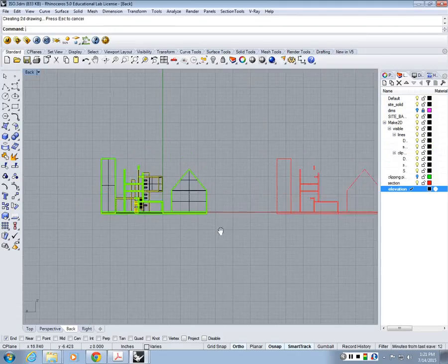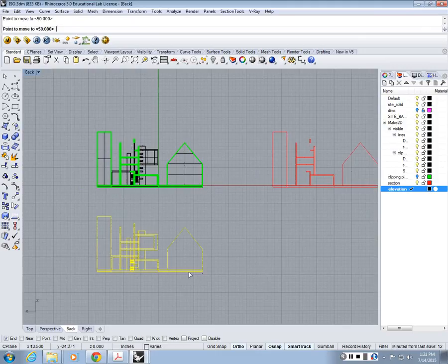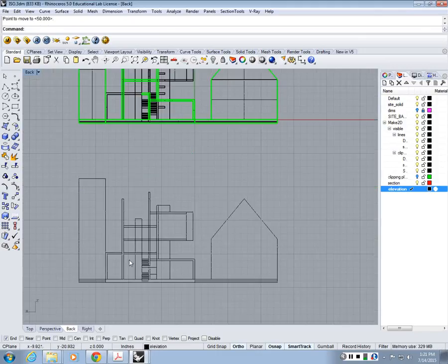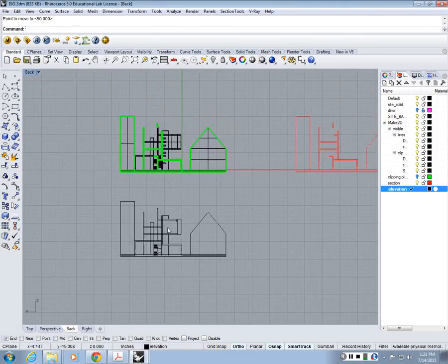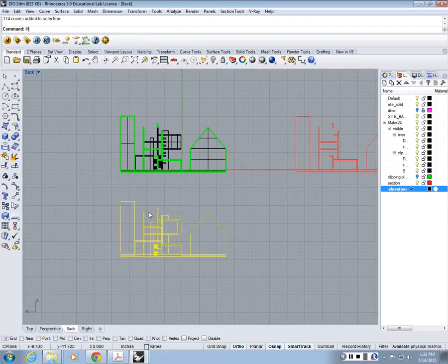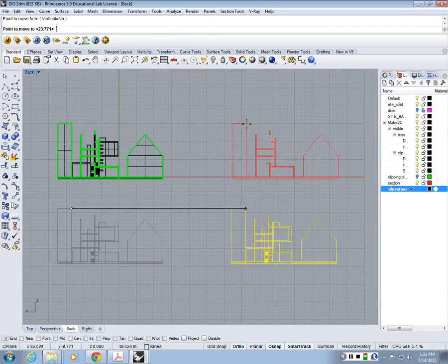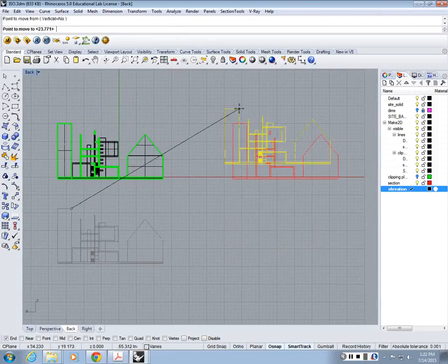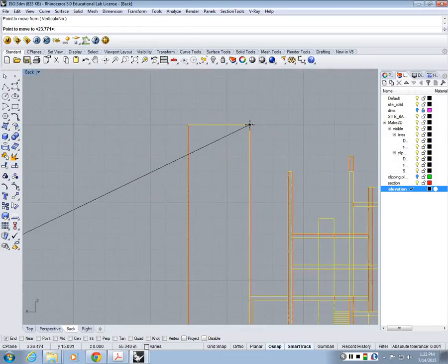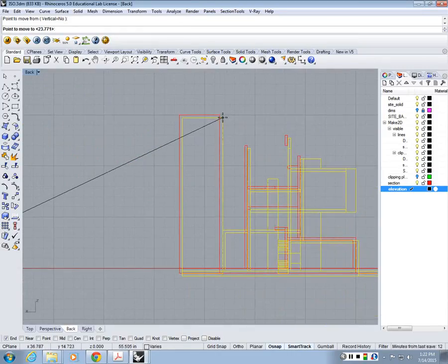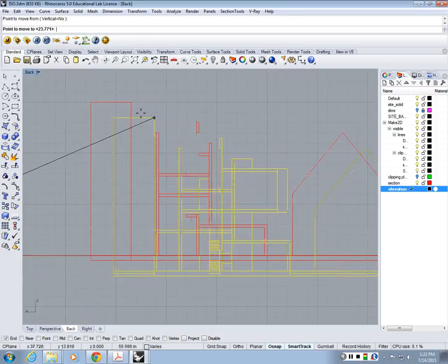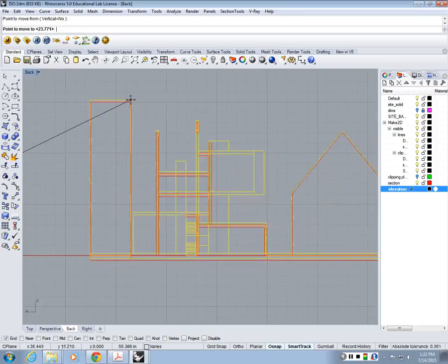And I should get some elevation lines. So this is my elevation lines basically, right? So where does this go? This overlaps with the section, right? This should go right here because they need to overlap. I'm still getting some similar geometry, but we're going to filter through them, right? Because elevation and section need to be on different layers so that we can apply different line weights.